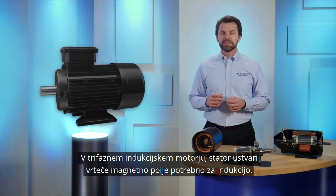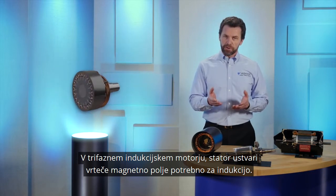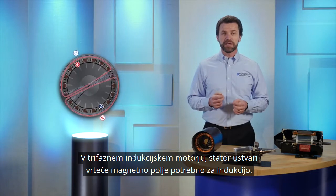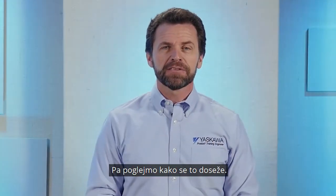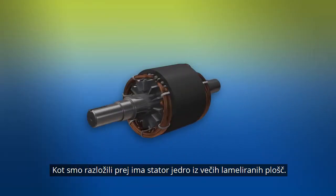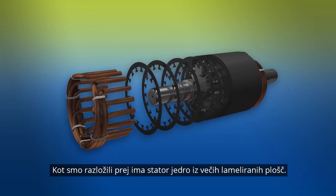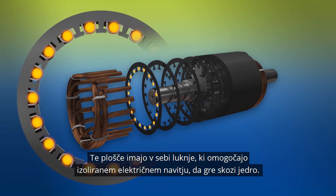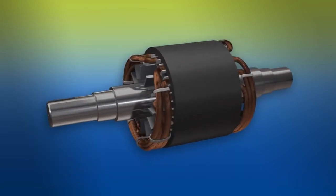In a three-phase induction motor, the stator produces the varying, or to be more exact, rotating magnetic field needed to initiate and maintain the induction process. And let's look at how that's accomplished. As we described earlier, the stator has a core of individual laminated plates that are laminated together. These plates have slots in them, which allow insulated electrical windings to pass through the core.